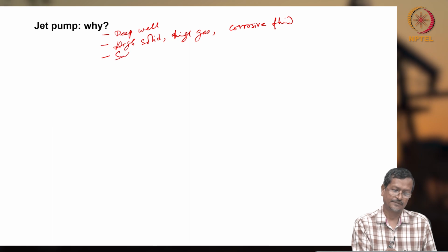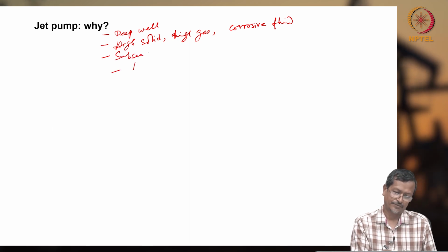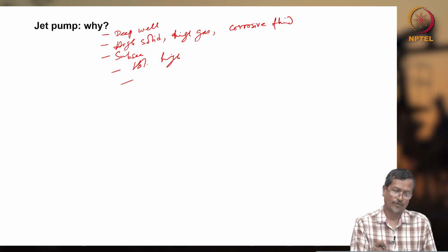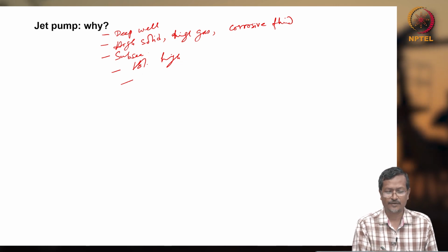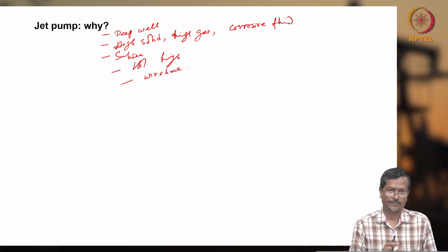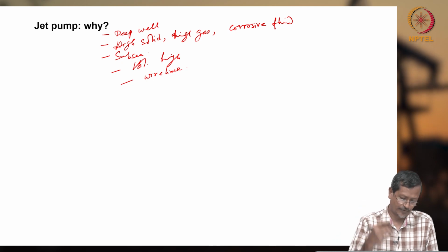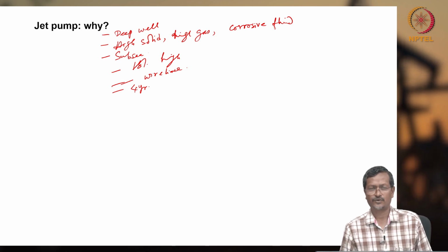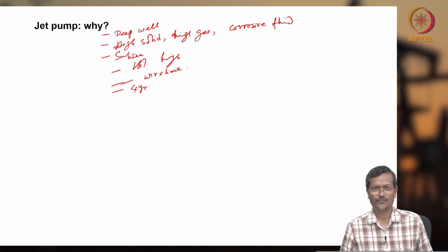Subsea production is possible, and volume of production can be high. With a short and compact body, retrieving or fixing, wireline operations, etc. are possible, because only the nozzle part has to be removed or fixed. Operation life is also very long. Do you remember the PCP I already told you about? Its operation life is about 4 to 6 months.